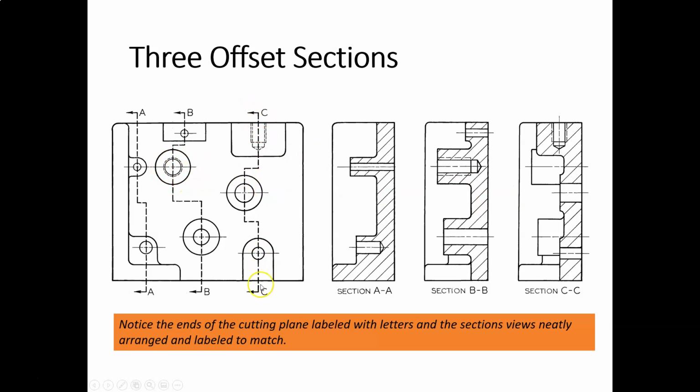And then finally, CC, same thing. We have this horizontal hole right here. Well, vertical, but I'm thinking that this is probably the bottom. That's why I called this horizontal. Tapped hole, tapped blind hole. This is a tapped blind hole too. It doesn't go all the way through. And then we have the cutting point line cutting through here, jogging over, cutting through here, and then jogging back.